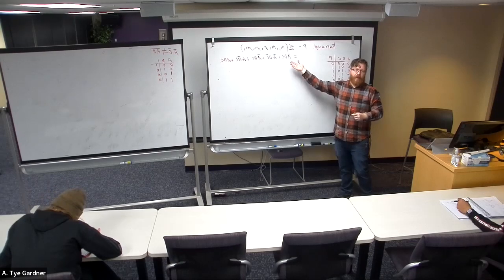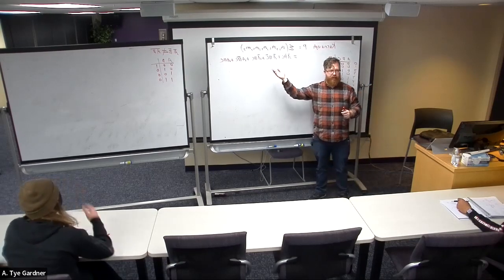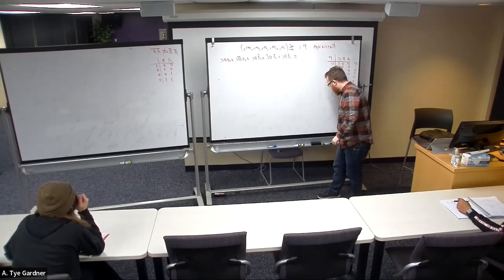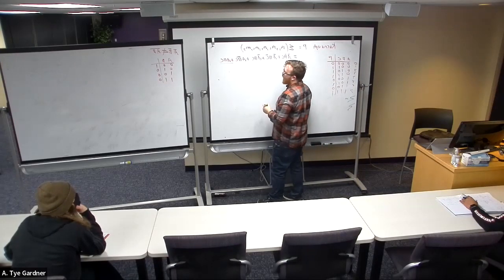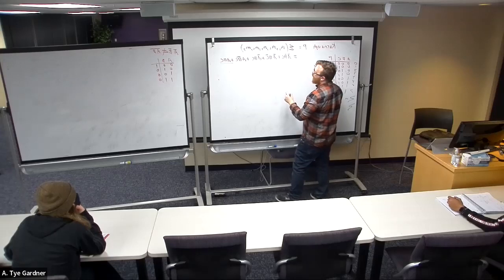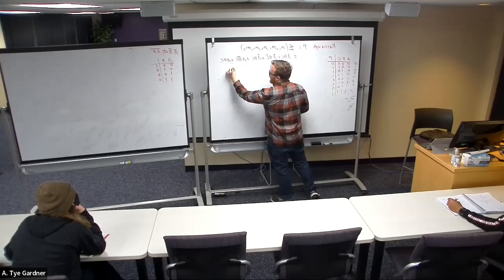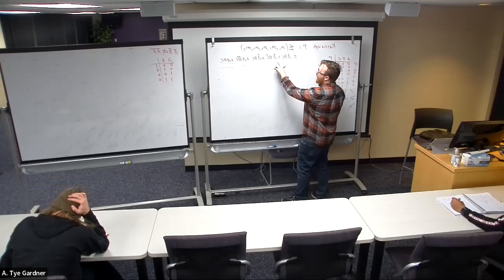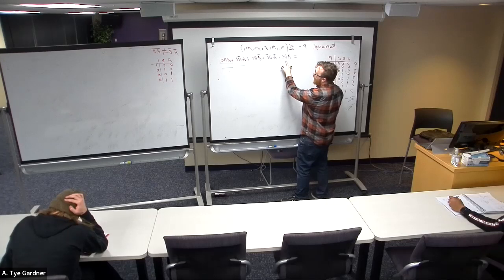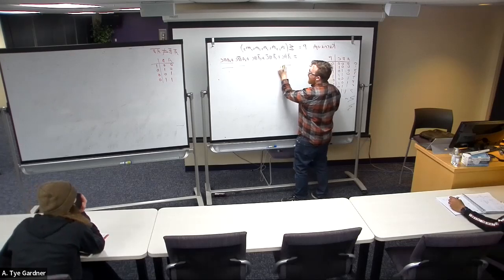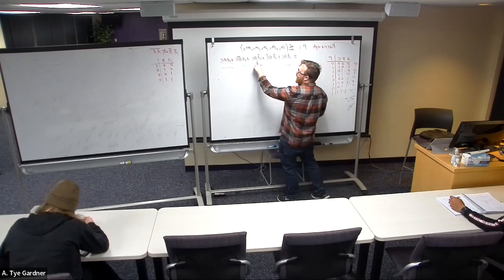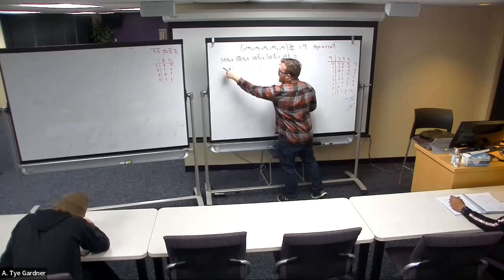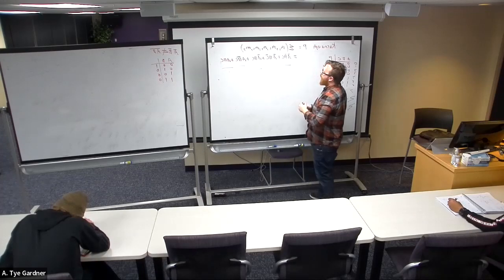We get that, and then we start looking for two of these terms that are logically adjacent, because they will simplify using Boolean algebra. So I look and say this and that are logically adjacent. This one and that one are also logically adjacent. This one and that one, because only the B variable changes, are logically adjacent. So I can pull that one away so that I can use those two together without having a redundant term.